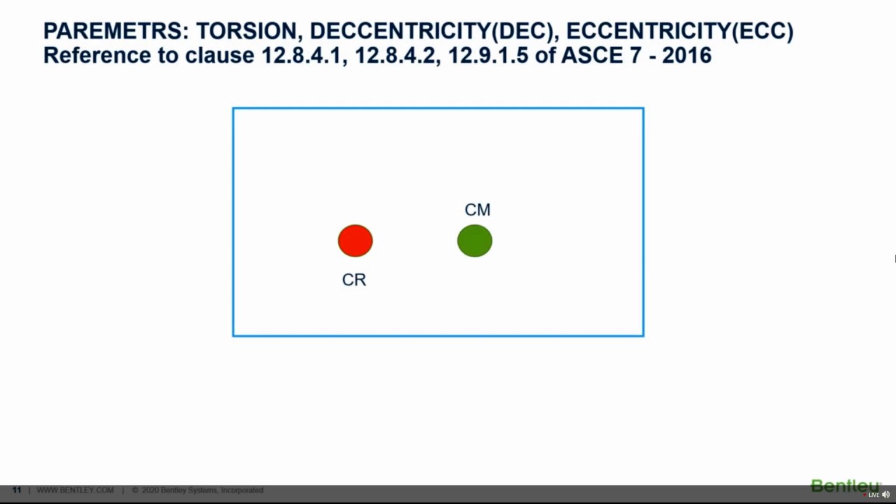Now, considering what we have learned till now, let us see how the response spectrum load cases will be specified. We will not be considering the negative direction factors, and we will be considering them through load combinations. So we see that we have specified the response spectrum cases thrice in each direction, x and z, making 6 response spectrum cases. So why do we need 3 in one direction? Well, let us look closely at the spectrum case.